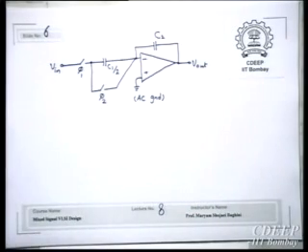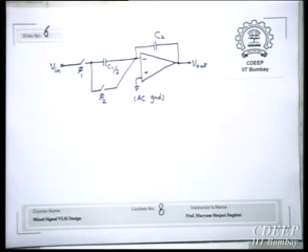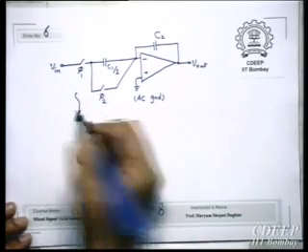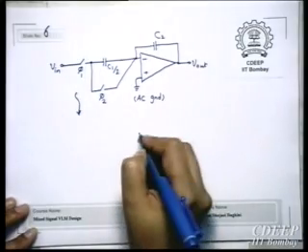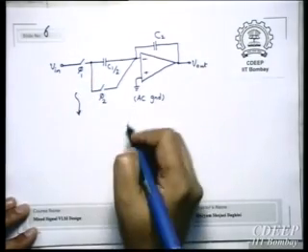Another thing is we want to have a memory of xn minus 1. And then send the charge related to xn minus 1 also here, right? So to do this, we need to have another capacitor. So we add one more capacitor. So this was the first part, right? So we modified it in this way. So phi 1 and C1 upon 2 will be there.